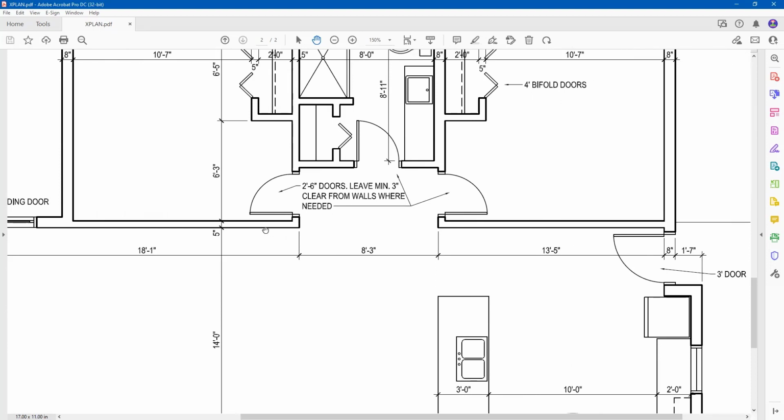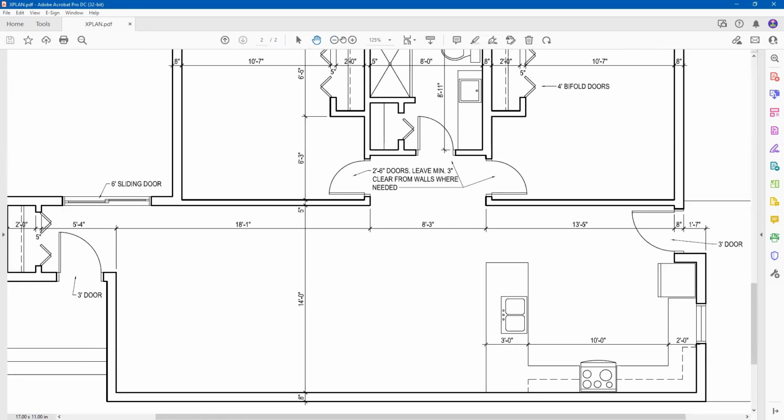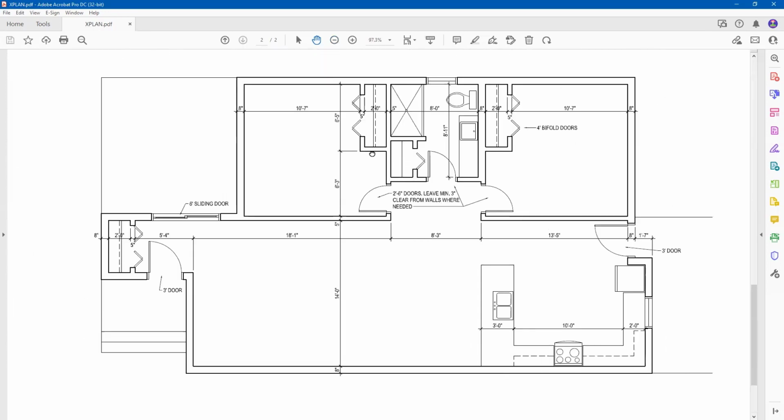And then my interior walls are 5 inches, so I can then offset 5 inches, and I'll have this wall going through. And then once I have that, I'll be able to use these dimensions. I'll be able to put in the opening that I need. That's my next step. And I'm just taking this nice and slow to help you think this through.